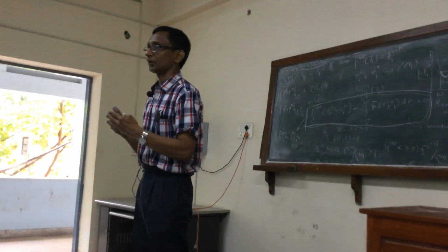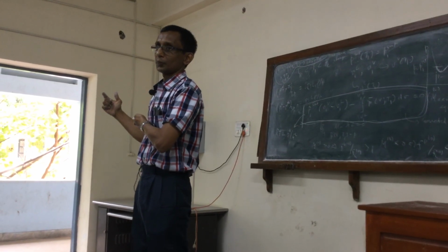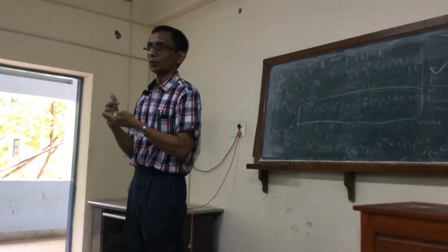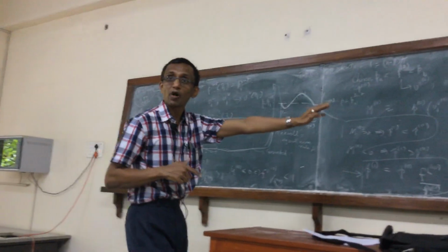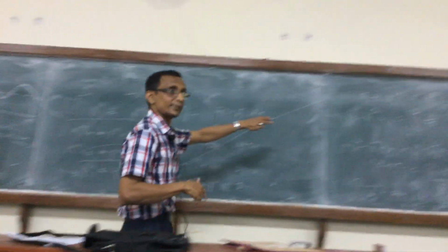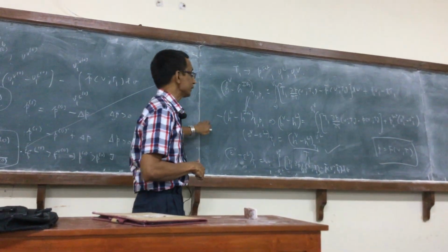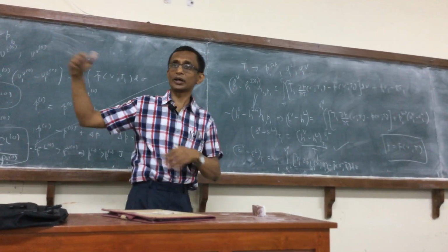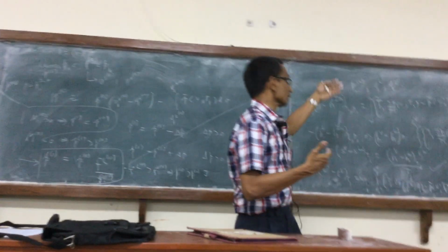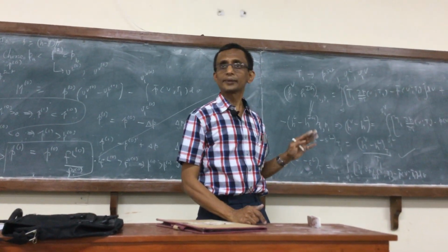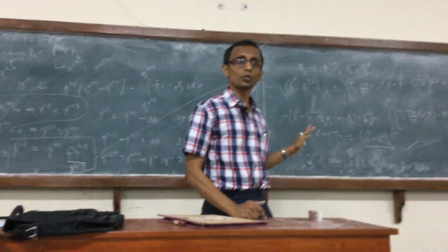For any change of state within the gas phase, the moment you have a transition from the gas to the liquid phase in between two states, then you have to take the phase change into account, and we seem to have got some formula at least, even though these have to be corrected later on. But right now we have got some formula that calculates the phase change, and we have seen for that important is to calculate first the saturation pressure, and then you can calculate all these properties. It does have a fundamental flaw, all of these formula, but we will see how to correct it later.